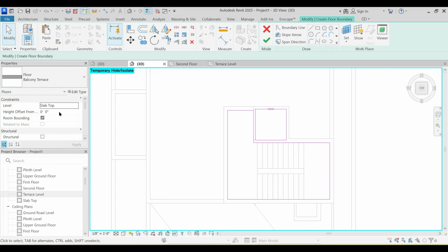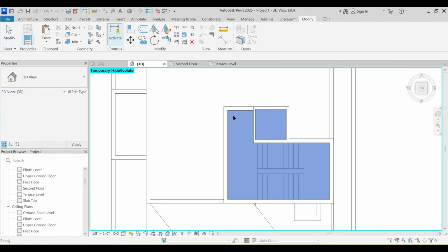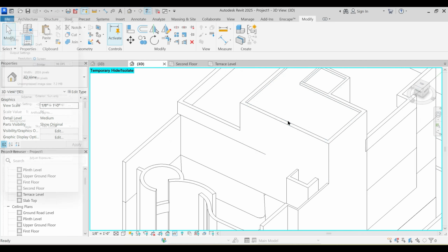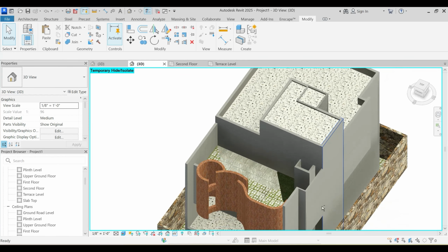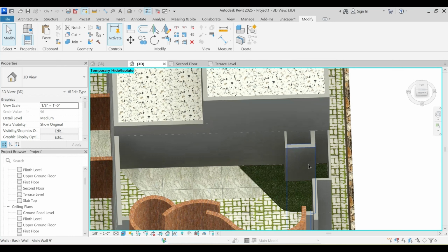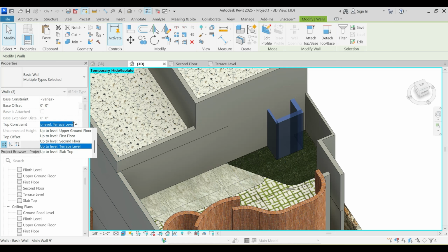Okay, and just say that, yeah, give it minus 6 inches. It's finished. Don't attach 3D, or not this 3D, this 3D, I guess. And R enter, done. Final. Okay, perfect. This three walls would stop at second floor with the top offset of 3 foot.